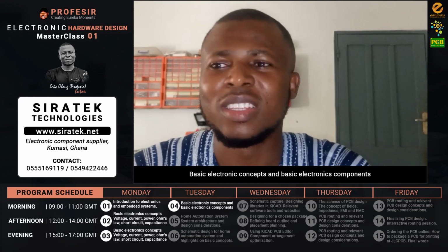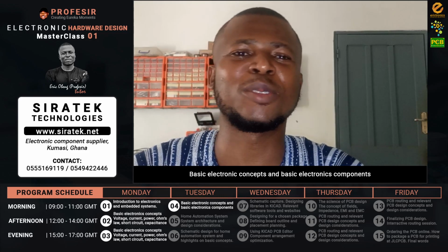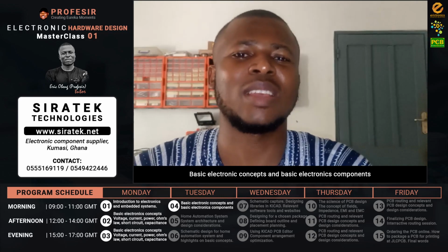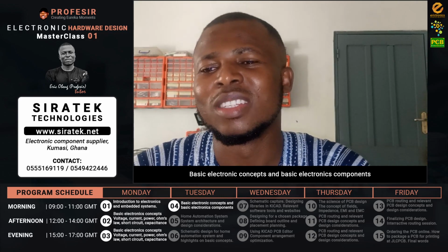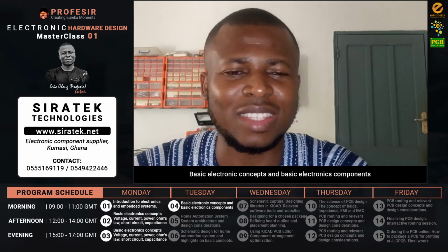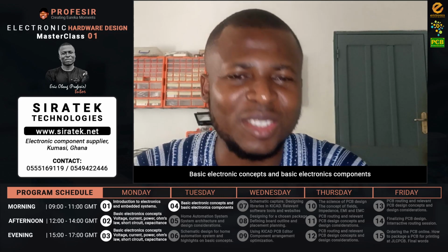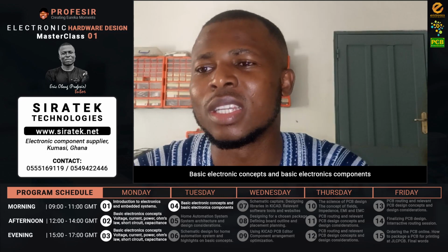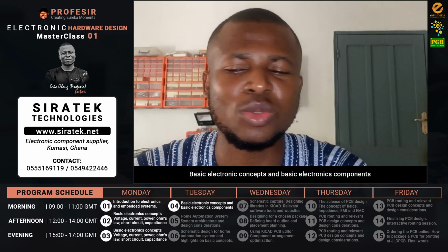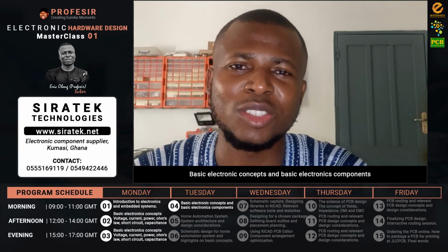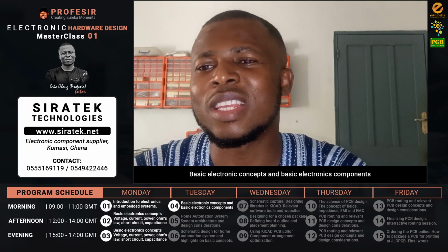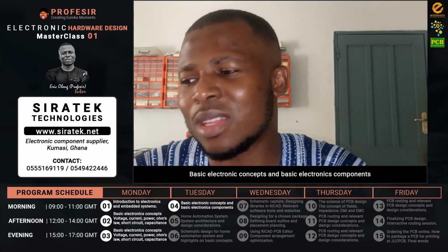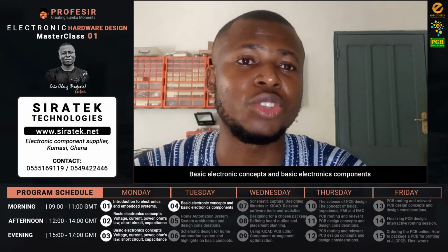Okay. So I searched online and realized that, oh, so Proteus also has a PCB editor. So that same night, I started learning Proteus, and it was quite interesting. I found the components that I needed, and you could also do simulations with Proteus. Okay, so it was quite interesting until I finally printed out my board, etched it, and I realized that I didn't get my drill holes.